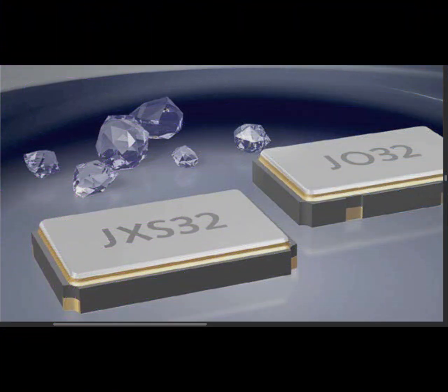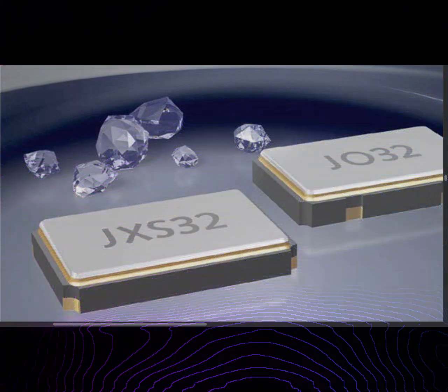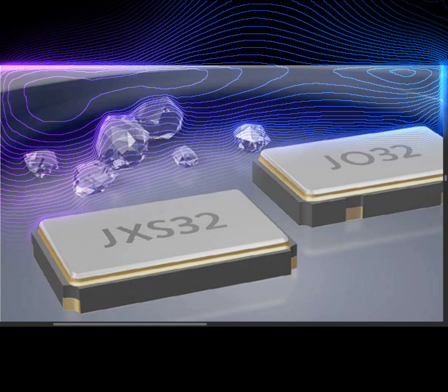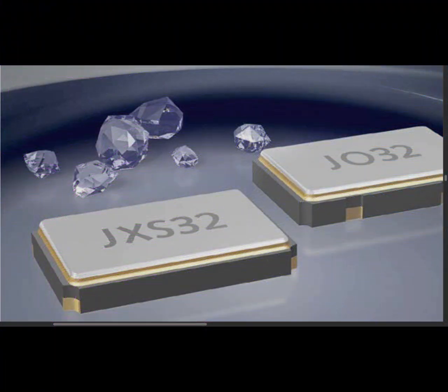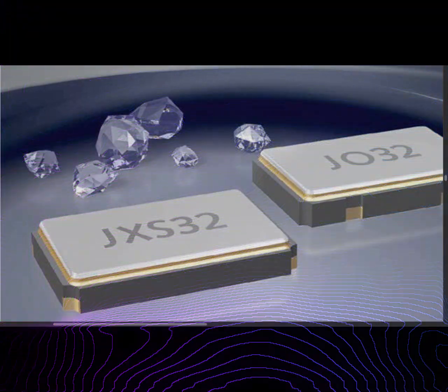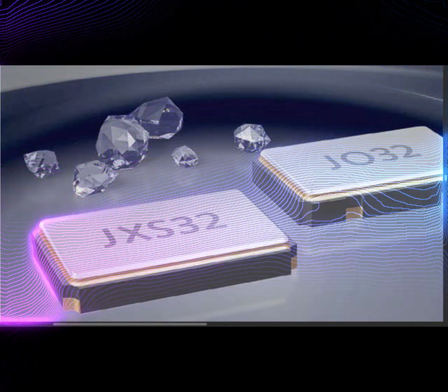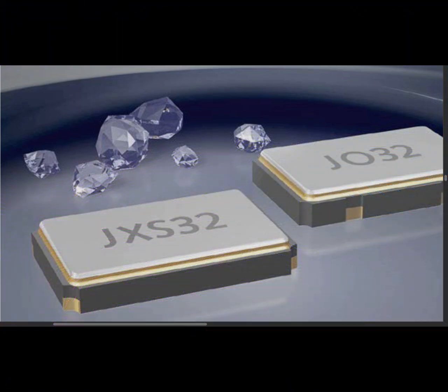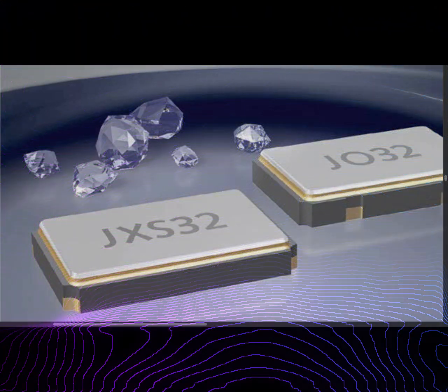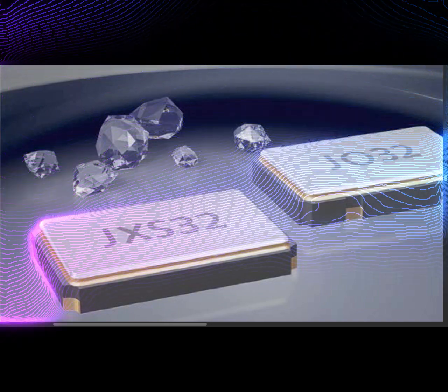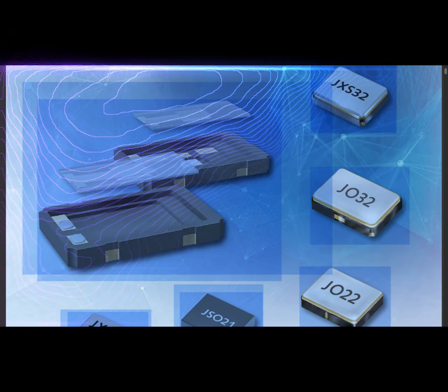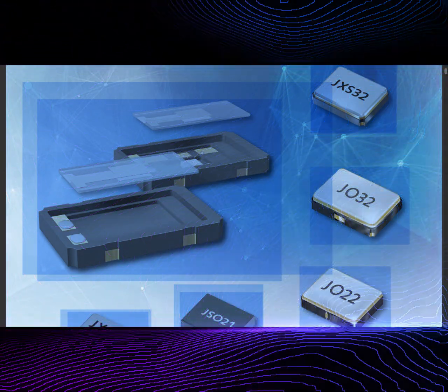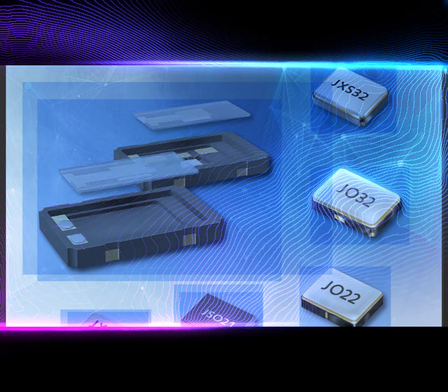As stated before, the required thickness of a blank can be estimated as the number of half-wavelengths of the acoustic wave that should fit into the thickness plane of the crystal blank. In addition to the thickness of the crystal blank, the propagation velocity v of the acoustic wave inside the crystal material is needed to estimate the resonant frequency f.